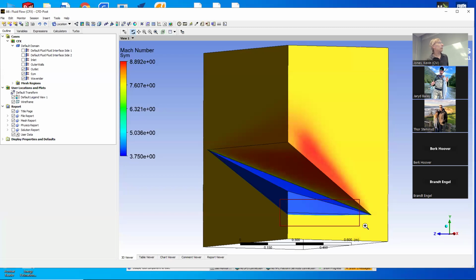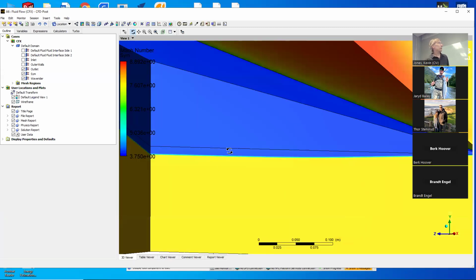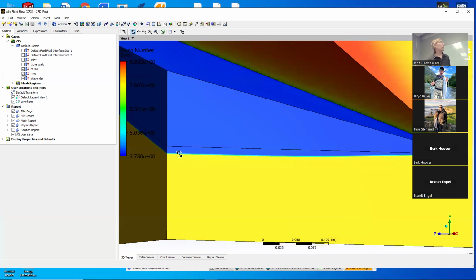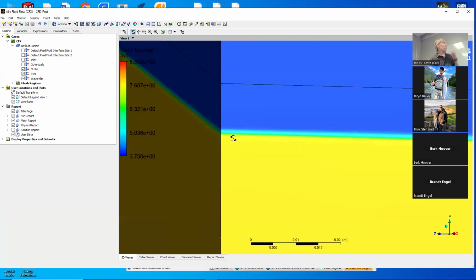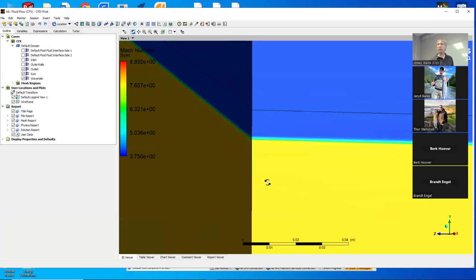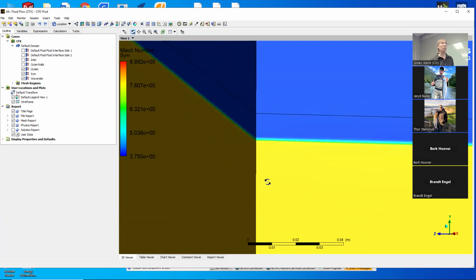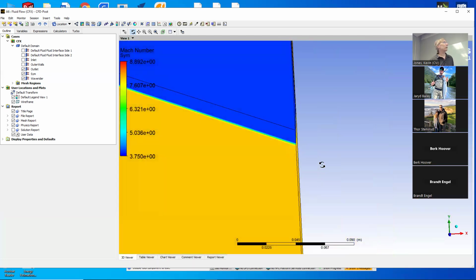So you remember in our domain, this is the break line between the inner and outer blocks of our mesh. And we designed it for the on-design case, so the shock would be right on there. And it was certainly inside of that fringe. It's spread out a little bit, but anyway, that was definitely on top of this. But at 5 degrees now, we've shoved the shock out away from where it's supposed to be. It's actually a little bit curved.